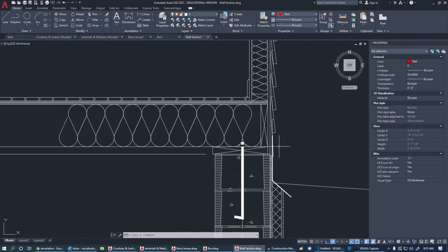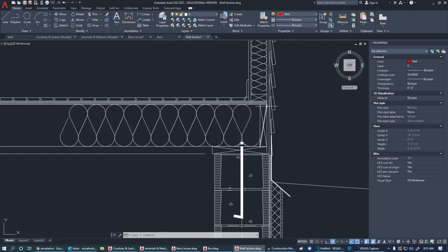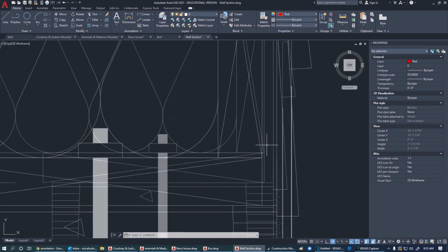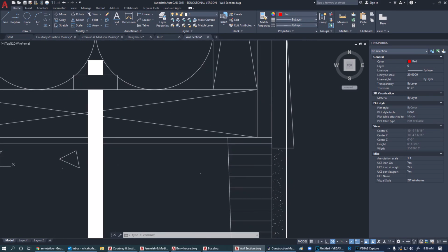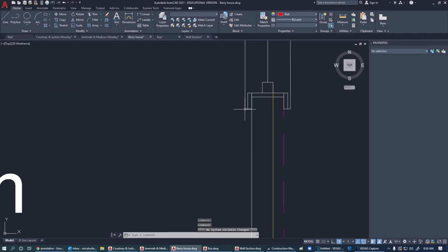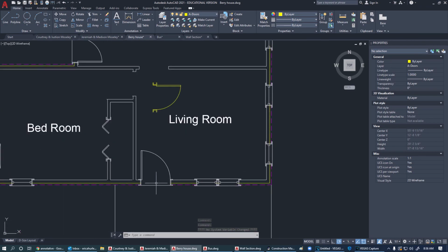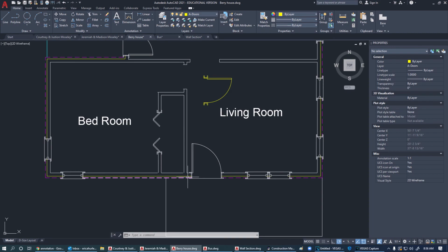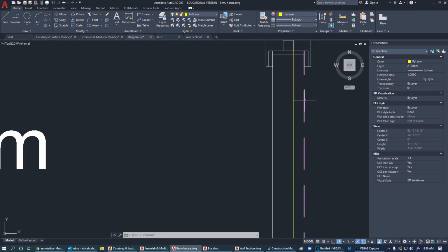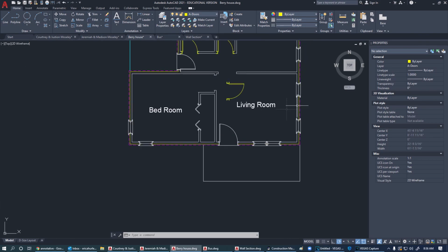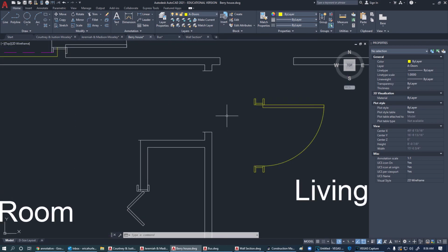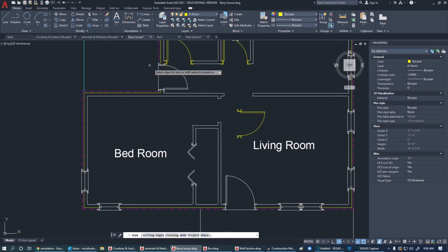And in this case, since I've already taught you how to do this, let's just say that we're going to do it this way. We're going to put the 1/2 inch OSB to the end of the block, or to the edge of the block. So we'll just leave this wall at 4 inches. And so technically we could move this line in a 1/2 inch as well, but I'm not going to at this point. So I want to just clean this up a little bit.